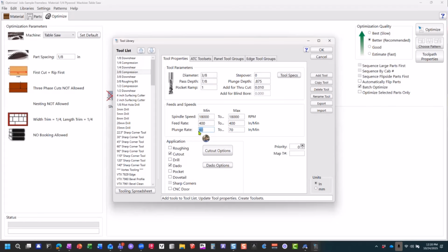To give you an example, say you're doing MDF doors and you're using a sharp corner on the doors. I've had some people say, hey, when I do the ramp out, it looks like the tool's actually over traveling the lead out when it's doing the clean out on the corners. That sometimes can be from some play in the Z axis. So I recommend they slow the plunge rate way down, and that will help not have the spindle over travel the corner of the operation. It's just a one fix.